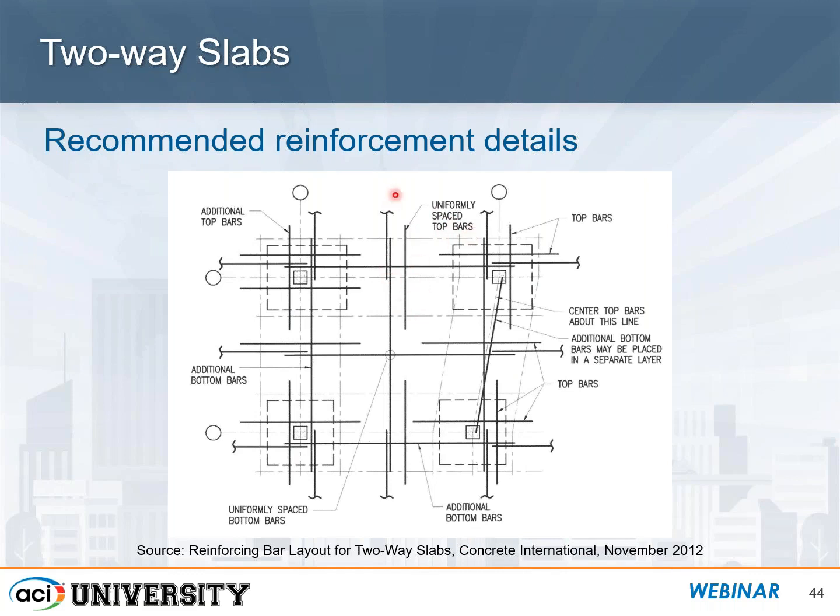And you certainly don't have to show the bars on your construction documents. You can have a note that tells you what the bar size and spacing is in both directions. And then what I usually like to do is provide any additional bars, including any skewed bars, that are easily seen on the drawing itself.